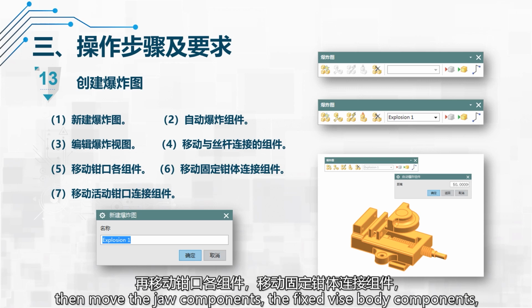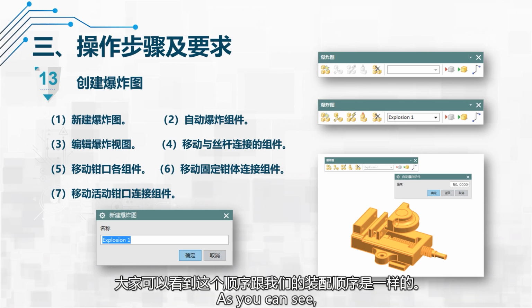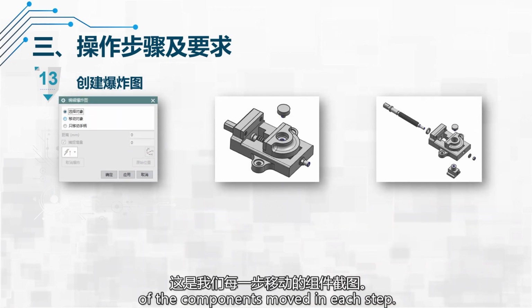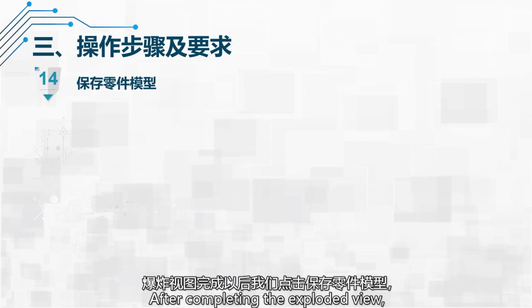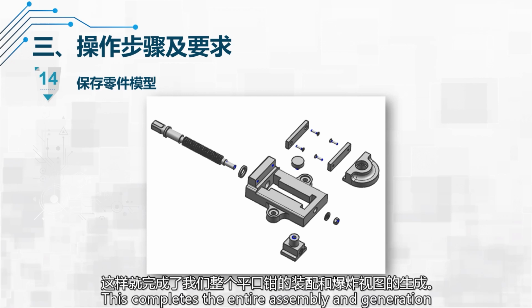Then move the jaw components, the fixed Vise body components, and finally the movable jaw components. As you can see, this order matches our assembly sequence. Here are screenshots of the components moved in each step. After completing the exploded view, click Save Part Model. This completes the entire assembly and generation of the exploded view for the bench Vise.